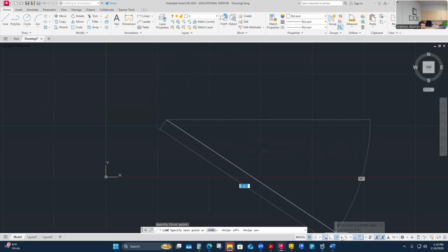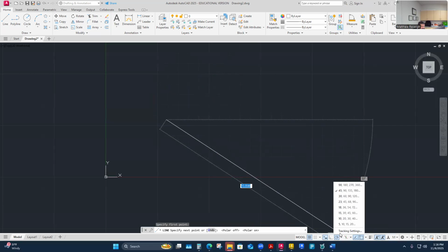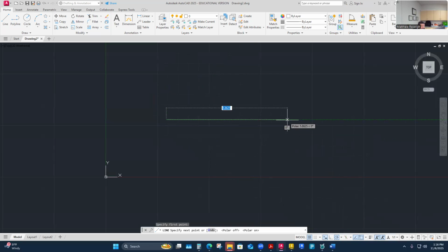That's because if you click this expanded list next to snap tracking, we can have different snaps show up, all the way down to 5-degree increments and as coarse as 90-degree increments or even coarser. I don't know what yours is set on by default. Mine was last used on 45s, but if I click 5, then every time I move 5 degrees I'm going to get an accurate snap to those degrees. So if I see that green ray light up, I can be pretty assured that the program is going to keep me in that angular alignment perfectly.